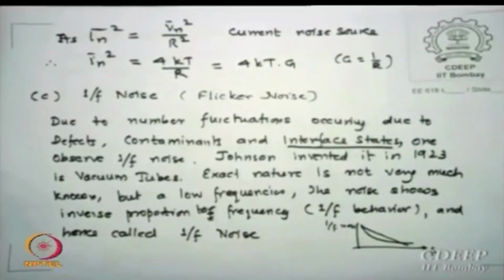So you find in a bipolar this noise is not as dominant as in the case of MOSFET. The 1/f noise comes in the bipolar in the base transport only, because there is a fluctuation in base, but that is comparatively much weaker in amplitude compared to MOS 1/f noise. So if you are looking at MOS circuits, you do not neglect 1/f noise. If you are using bipolars, then do not lose shot noise, because that is not there in the case of MOSFET. Okay?